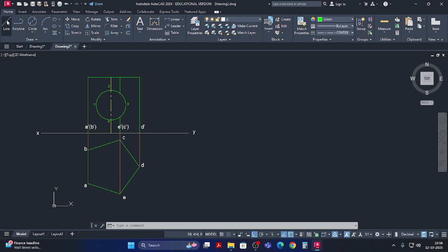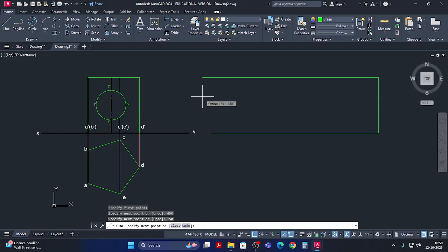Okay, take line and you go straight to this and you draw. We'll change the line type. Line type continuous or by layer. Okay, now take what is the one side 90 mm, then 5 sides 450 mm. 450, enter. This side height of the pyramid prism 150, enter, and this is 450.